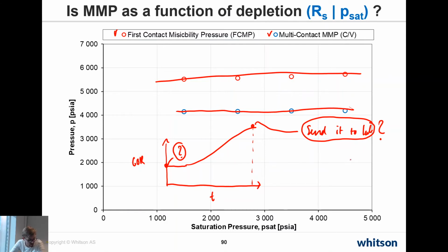So don't try to over-engineer necessarily to have a representative reservoir fluid composition. And the reason for this is that, as I mentioned, the MMP is not a strong function of the GOR or the solution GOR, but what it's actually mainly a function of is the distribution of, call it, C5 plus components. So that's the distribution of those components that exist in your liquid.